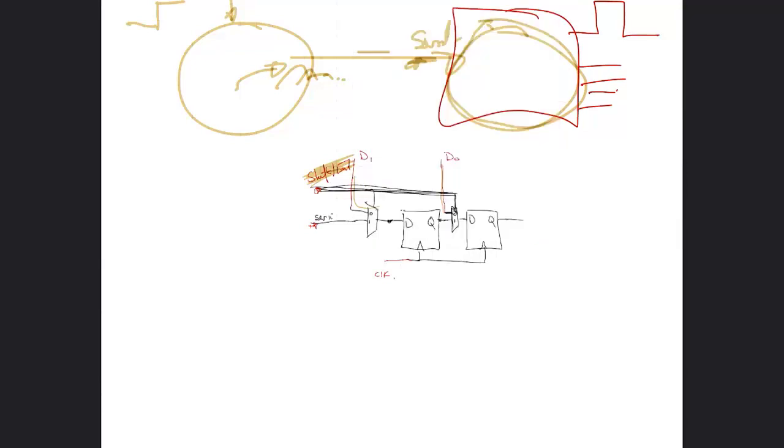Oh, okay. Yeah, thanks. The data ready, I didn't understand it properly, but now it makes a lot more sense. I'm gonna share my screen. Do you still want to? For the transmitter side, yes, for the start TX. Okay. While you do that, I'm just going to make a comment. That data ready, you will see, is the thing that latches the display on the 7 segment. So that's the thing that causes the flip flop on the display to show the value. So as soon as this data ready goes high, it displays whatever was on that data port. Okay, go ahead, Mr. Shenny.